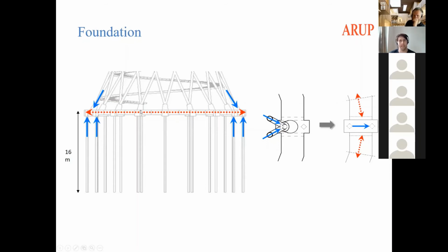And what's interesting here is the action of the concrete ring beam. So when we have the tower in compression, the whole concrete ring beam is going to be in tension, making sure everything is tied together. So if you take your stick model from the first slide, and try to push down from the top, all the individual concrete plinths would try to move away from each other, but the concrete ring beam is tying that together.